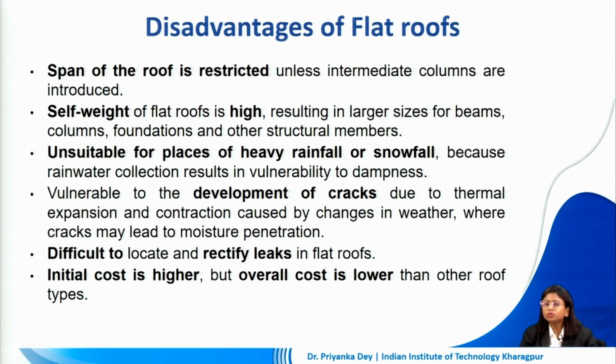It is unsuitable for places where very heavy rainfall or snowfall is evident, because of the rainfall which actually collects. This can increase the vulnerability due to dampness. So in those situations or places where a lot of rainfall happens or snowfall very commonly happens, we have to opt for a pitched roof instead of a flat roof.